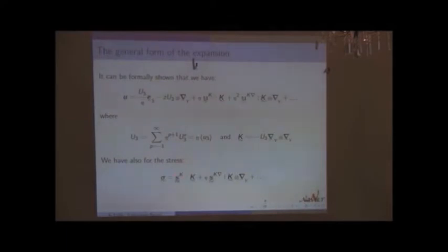and going higher order. So this guy is the stress related to the curvature tensor. So this is the in-plane stress because of bending, and this guy, we just derived it, is the transverse shear strain related to the gradient of the curvature. All right. Sorry, inevitably it becomes complicated.